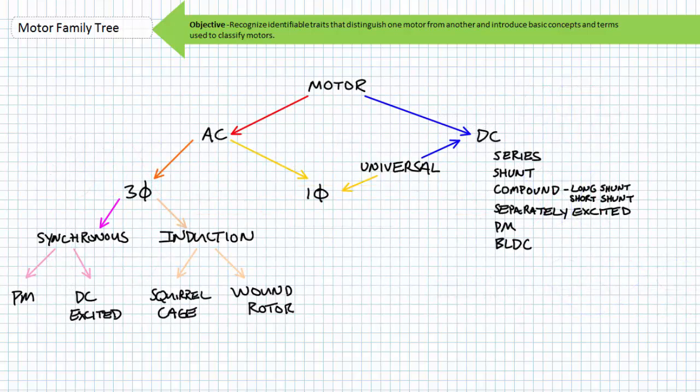Straddling this no man's land between the single-phase AC motors and DC motors is the universal motor. As the name implies, it can be run on DC or single-phase AC. Just like cutting a fish in half and sewing it to half a monkey, it doesn't swim well, nor does it ride a bike well, but it does both swim and ride a bike. The universal motor is really just a series DC motor, think commutator, with compensating windings on the field windings designed to minimize inductive losses when run on AC. We'll go into this device in greater detail later.